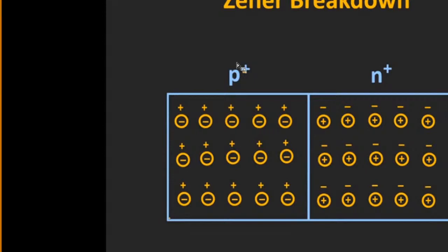But if I use the PN junction diode in the reverse bias condition, that means when I turn off the switch, there is still a leakage current, still some current is flowing. That is why it is not a practical switch. We cannot use a PN junction diode as a perfect switch. Now, how do we utilize the reverse bias operation? We can use the reverse bias by changing some parameters, so that in the reverse bias also we can perfectly utilize the PN junction diode. That type of diode is nothing but your Zener diode.